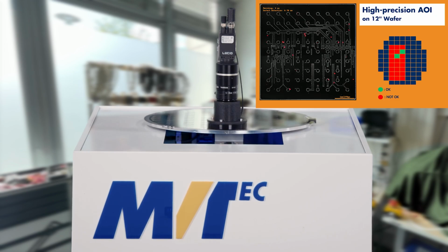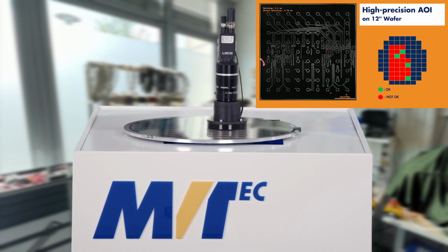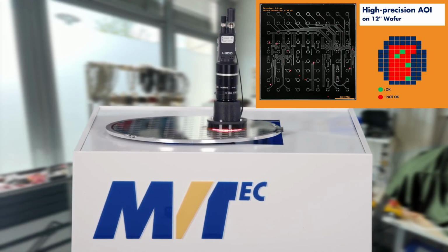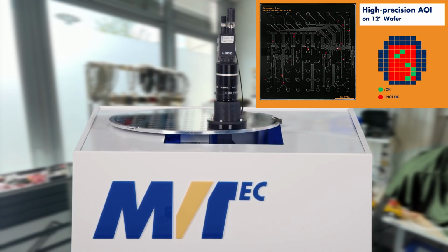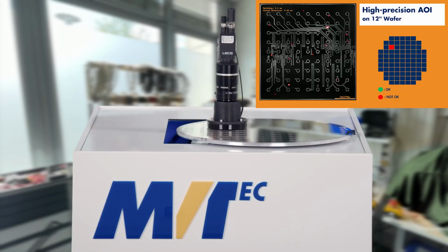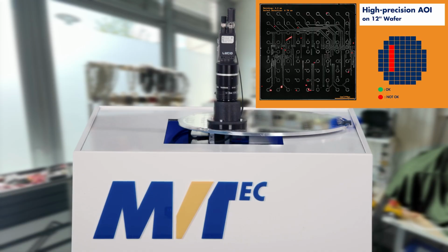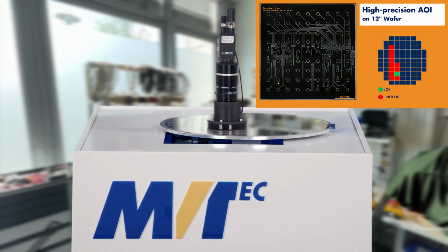On the right side, you have again the wafer map showing you the current location on the wafer, and the colors green and red tell you whether the chip was classified as okay or not okay. You can also see on the top left that the matching takes about 4 to 5 milliseconds, and the variation model is even below 1 millisecond, which is super fast.